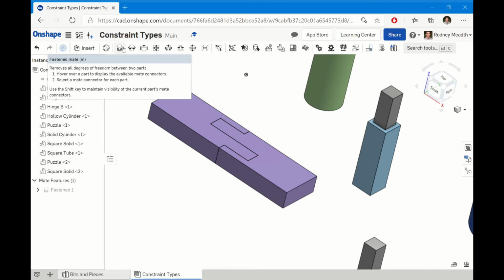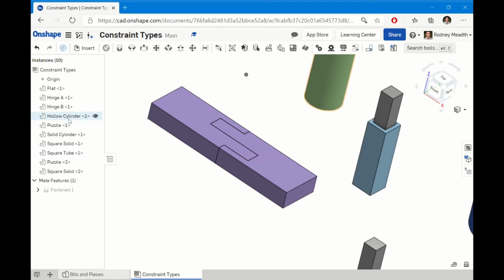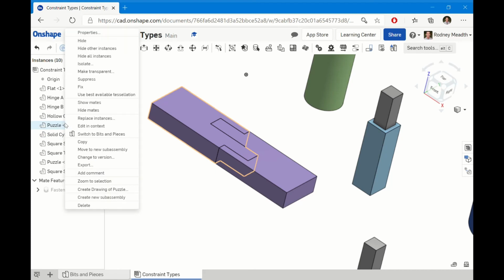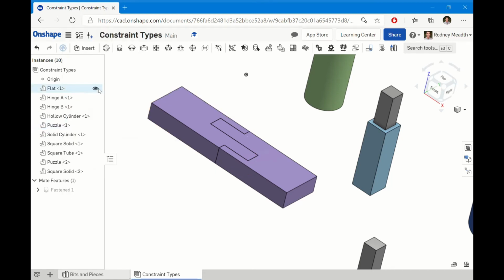Okay, this is the pole cemented into the ground situation. I'll also show you what I talked about in the last part of the video. I right click and I go to fix. Now I get this cool little symbol that pops up. Okay, this part is fixed. That means wherever it happened to be at that point, it's never going to move from there.